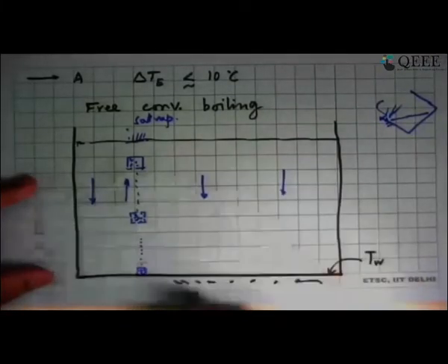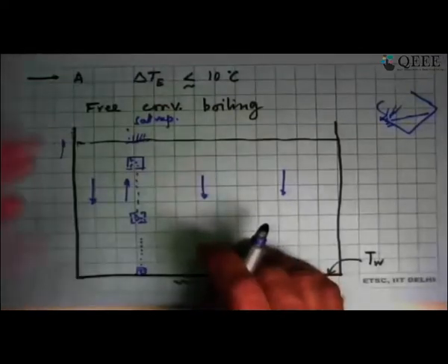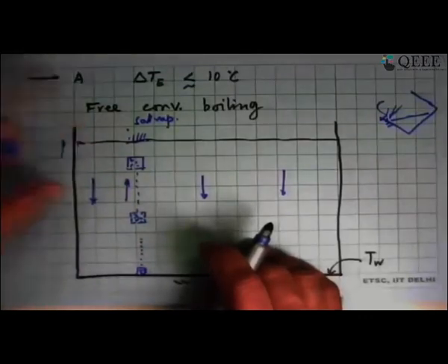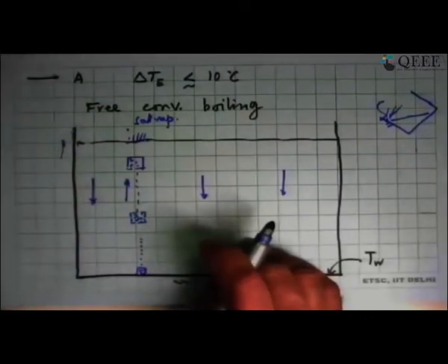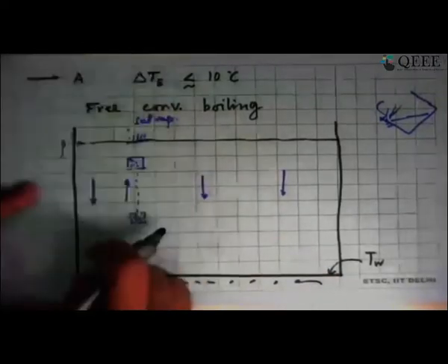And that is happening because when you're heating it from here, these walls got heated by the gases going up here, and this wall here, its temperature became more than the saturation temperature. So when you are trying to pour it, it starts crackling and it starts boiling over there, and you can see bubbles bouncing off and sometimes falling on your hand. So it was the case where the wall itself got hot.